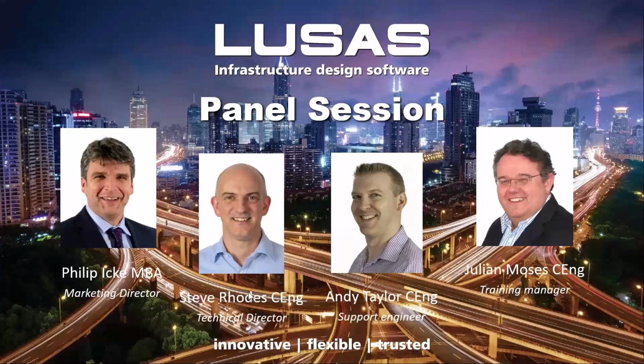Yeah, I'll take one, again, on the embedded reinforcement. The question is, why would I use this facility with the embedded reinforcement rather than just doing a simple beam analysis for my reinforced concrete structure? And the answer is, if you can use a reinforced concrete frame with beam elements for the type of analysis you want, absolutely go ahead and do that. And we have a reinforced concrete frame designer for beam models, and also a reinforced concrete slab and wall designer for shell element models. And if you can use those, then you absolutely should.